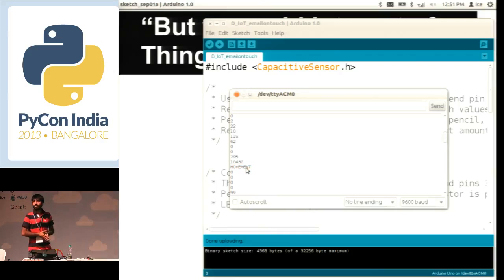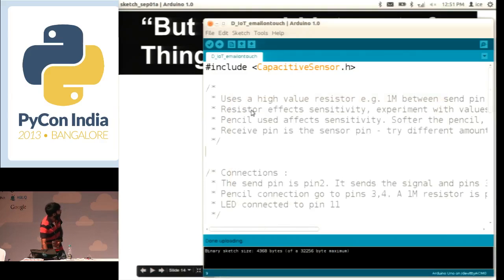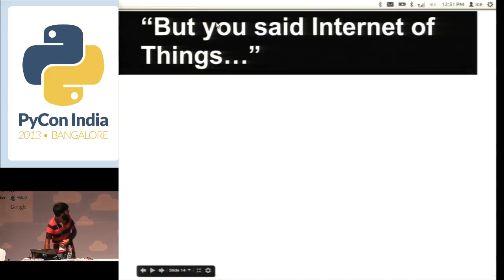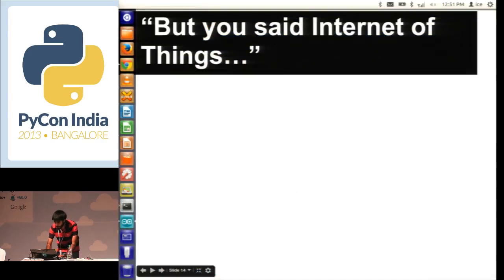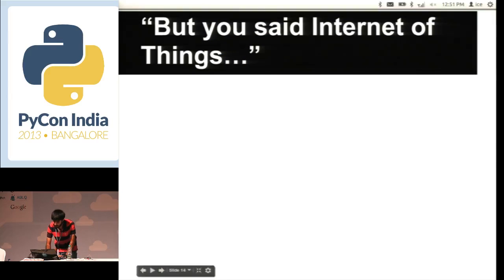So my Arduino side is working now. If I touch the capacitive sensor, it is going to send movement to your computer. And if again the time is too short, it is going to send too soon. Once I have this piece of code up and running on the Arduino, I can write a very simple Python script to read the data that is coming in.